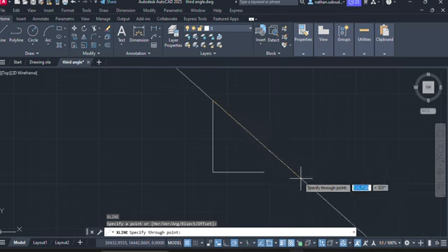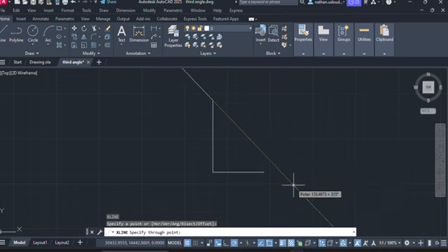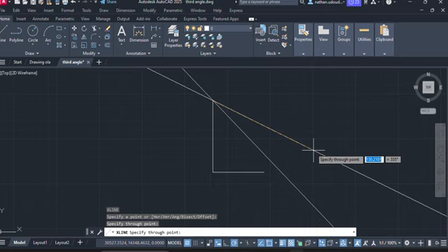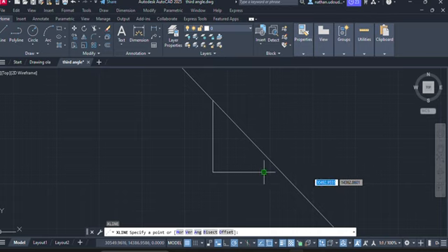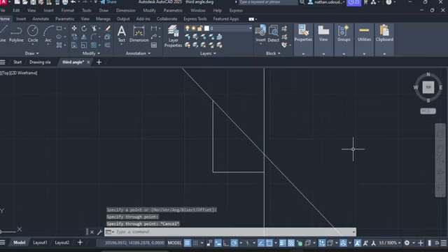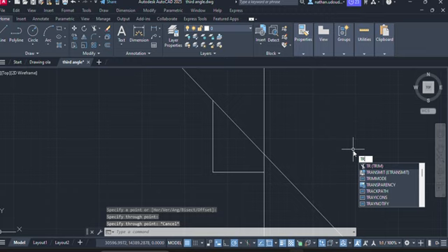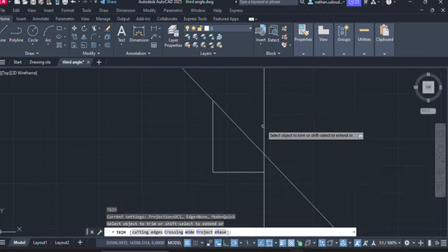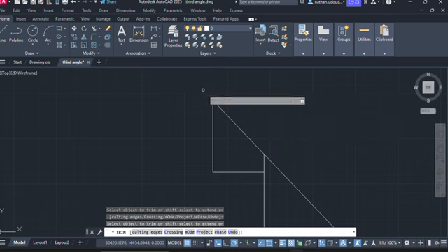We press it here. So now you can see that the dotted line is green, so that's your 45 degree, and then you escape. So L, enter from this point, and then vertically upward. You can trim it, TR, enter. So trim off the unwanted lines here.